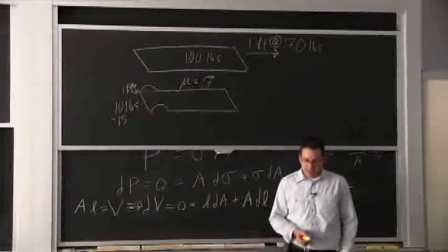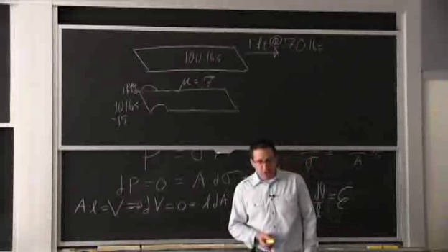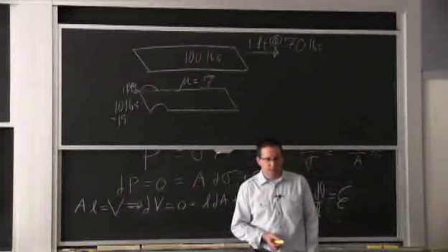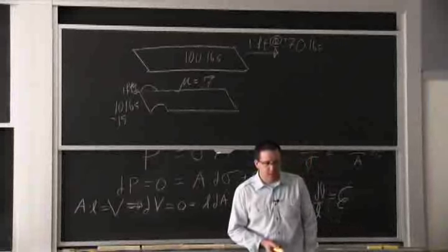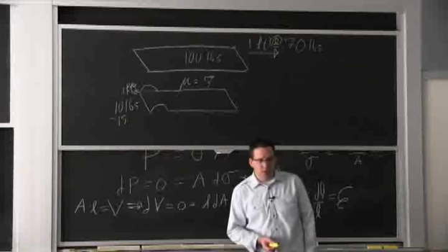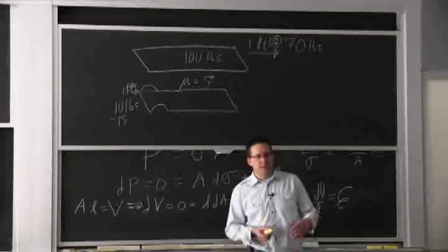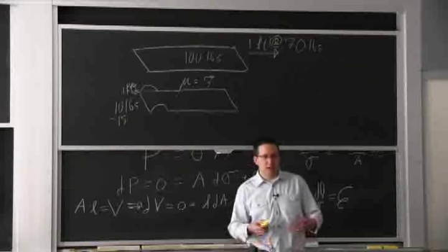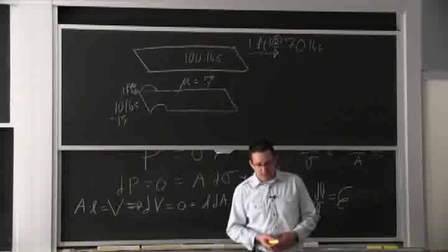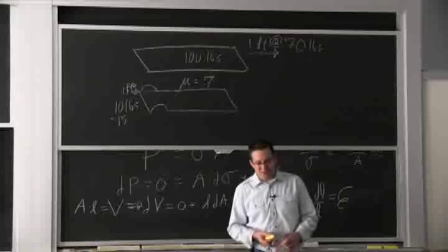For processing, you can control the hardening. And I mentioned a couple of times about temperature. You can put in small amounts of alloys that will also affect the dislocation multiplication and how it heals back after the fact. You can put in precipitates. So it's something that we engineer for a specific application.